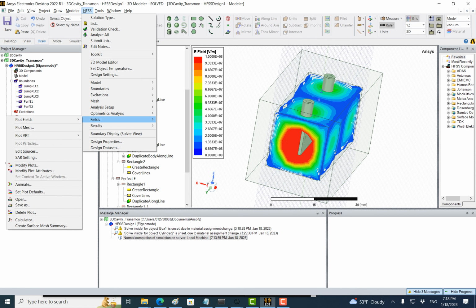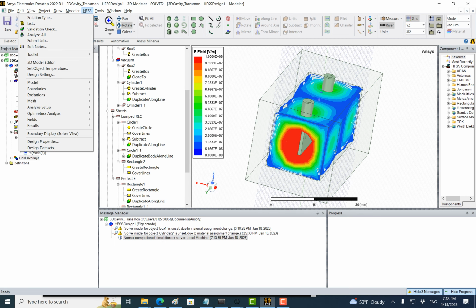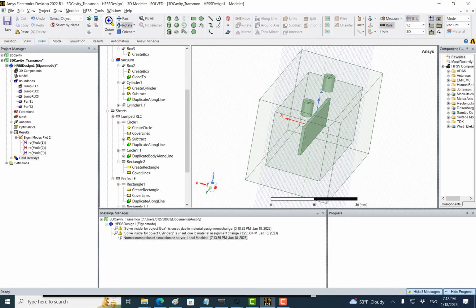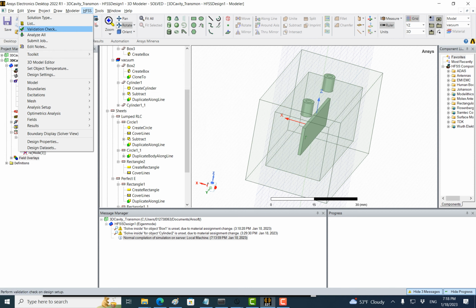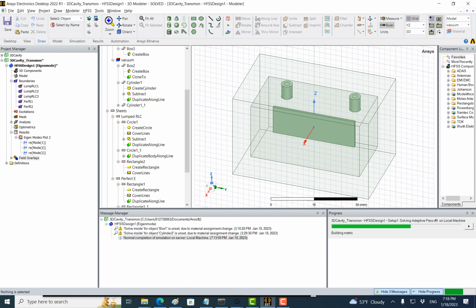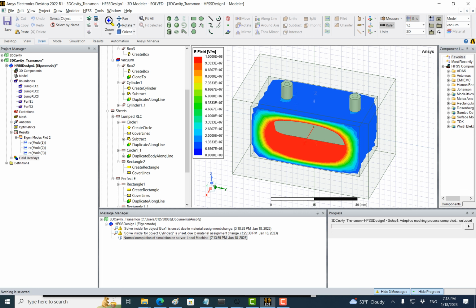So I need to go back, not to edit source, but to change the inductance. That's why you really want to have a variable. So instead of 5 nanohenry, I'm going to do 12 nanohenry. And because of this, I need to rerun the simulation. Basically, what I'm showing you is that when the inductance is low, the lowest modes are all due to the cavity. So you are not going to get something useful by putting the qubit inside, right? Because the qubit has a very high frequency.